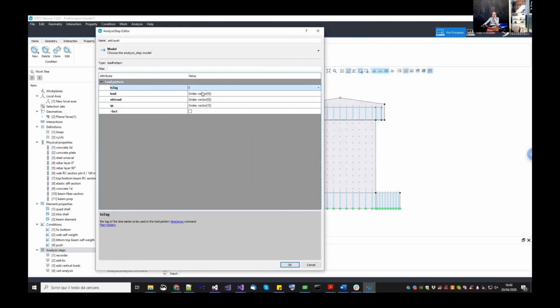The file that you will download has the cyclic. But actually, if you want to do some test in a monotonic fashion just before doing the cyclic test, because I typically first compute the monotonic envelope to make sure it is properly representing what I want, and then I do the cyclic. You can safely change from linear to cyclic. Why? Because both of them start at 0 and both of them finish at 1. That's why I use the load constant here. So I can safely change between one and the other. Okay. So now in this example, I have cyclic, but you can safely change to the other one.